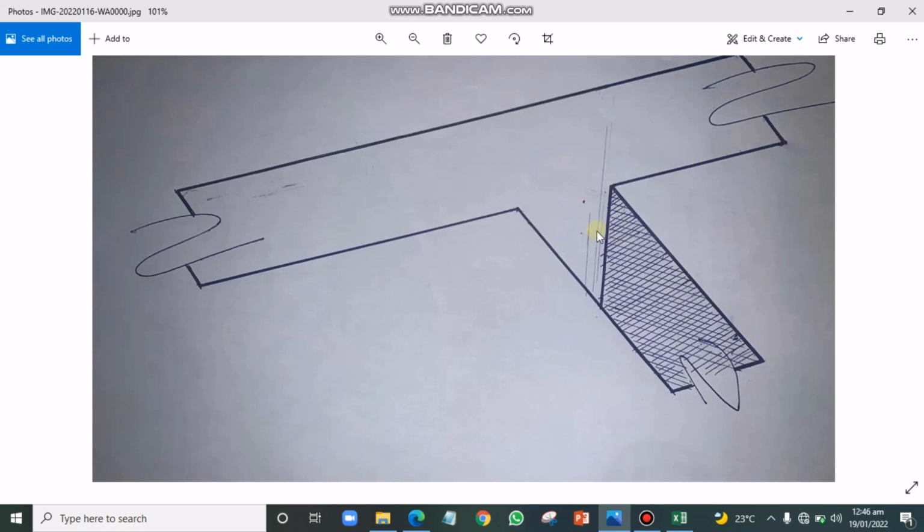So this opening here, this point of intersection, does not need a wood because the wood or the earthwork support will not do anything here. So we need to deduct this space here in each of the intersections on the plan. So take a look at it. The dimension is the distance from here to here, which is the entire width of the excavation, and then the distance from the top to the bottom, that is the depth of the excavation.